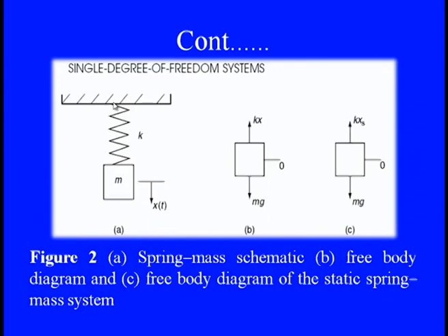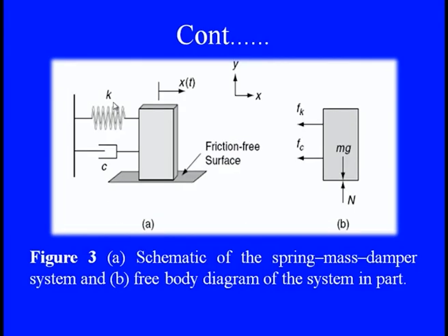So, you see here when we are trying to keep this single degree of freedom system, we know that we have a simple spring mass like system in which all the forces are being balanced out by the inertia, the inertia of the vibrating mass and the restoring forces. Or else, when we are providing the damping, the inertia forces are balanced out by the damping or the restoring forces.